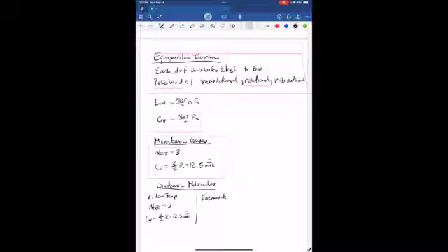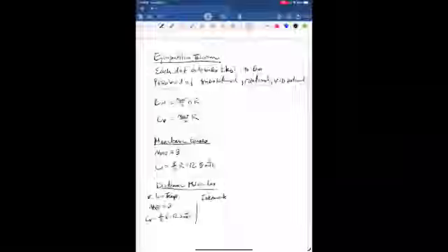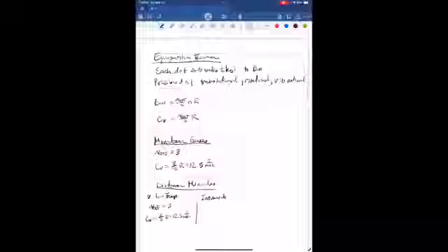they act, I believe they act like they've got, of course, translations. All gases have translations, but I believe they act like they also have vibrations. I'd have to look that up, and I don't have that sheet with me. Well, you know what? I can find it really quick. Let's see. I've got the table. So diatomic gases, nitrogen, yes, and oxygen. Okay, so they both act like they've got translations and rotations, but not vibrations. So let's just go through that.